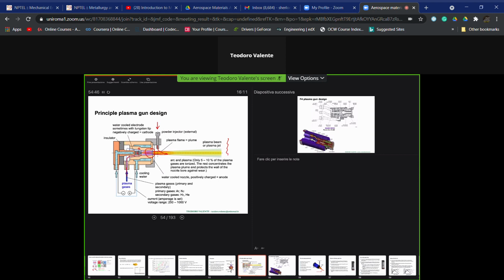But for example, this can let us understand how the flow rate of the gases which are used to transport the particles, as well as the size of the particles itself, are very important, because we could have, for example, particles which are making this, or particles which are making this, depending on the axial velocity, and that's depending on the flow rate of the carrier gas and on the diameter of the particle itself.